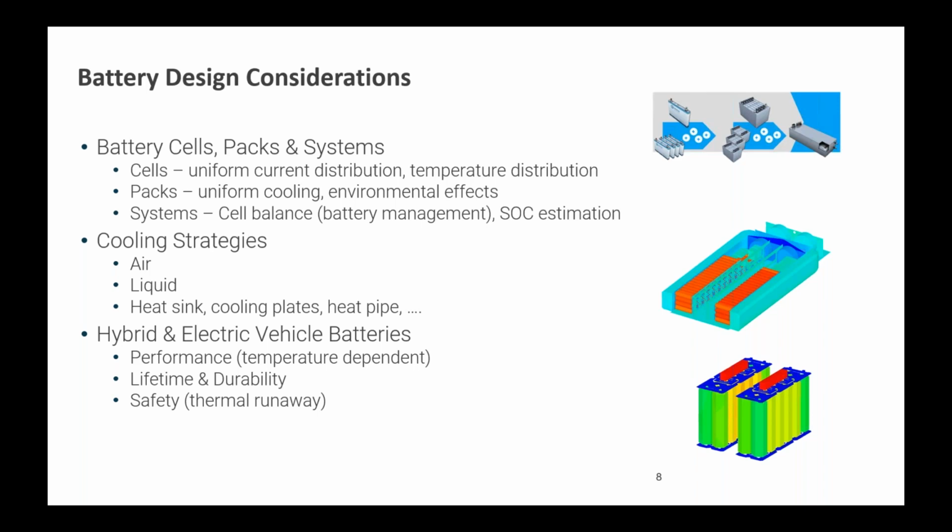Then you also have lifetime and durability, where we're looking at how long the batteries are going to last, and possibly how we might modify how those batteries are used in the vehicle to extend the lifetime of those batteries. Sometimes plan for secondary use applications where you can sell your batteries to a stationary storage facility or something like that. And also looking at what the minimum remaining capacity is that you can run your battery down to before replacement occurs.